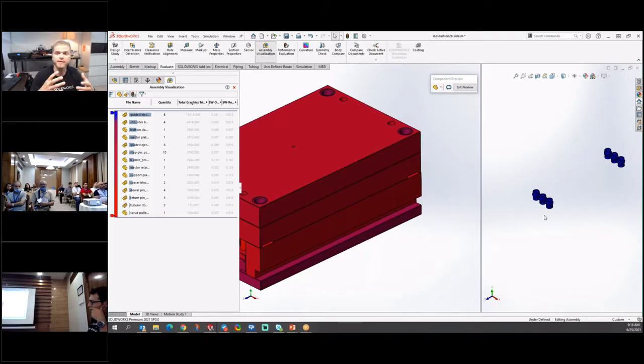This is an example, but on one of your files, it could be something with threads. If you've ever modeled something with a helix or threads, if you've ever modeled a plate with a lot of holes on the top, that can quickly become one of your heaviest parts in terms of graphics triangles. So for a customer who's seeing slowness, who's seeing an issue with an assembly, my answer would be, well, let's use this tool, find out what parts are the worst parts, and then suppress those parts and see if it gets better.